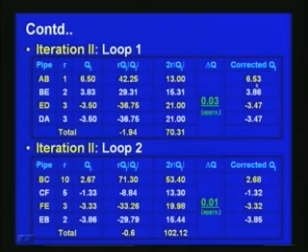It will now be 6.53, 3.86, minus 3.47 and minus 3.47. Now iteration number 2 for loop number 2. Similarly, what we did for BC, CF, FE and EB. QJ is already obtained from the earlier step, and here again B is 3.86, that is now minus 3.86 in this loop, and we can find RQJ modulus QJ, 2RQJ and sum it up.